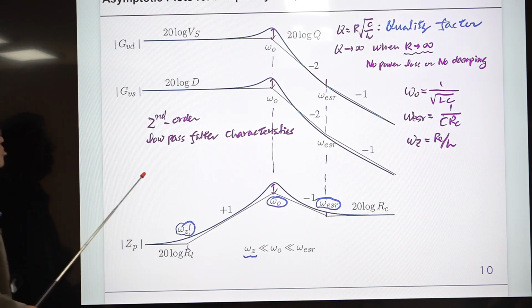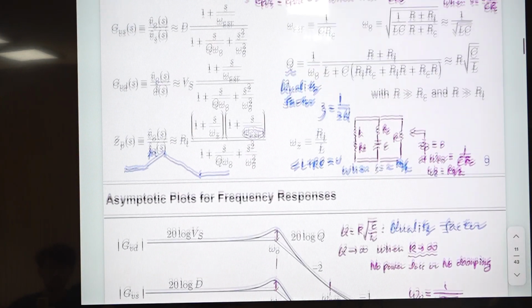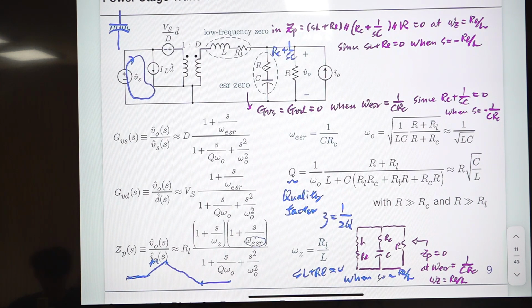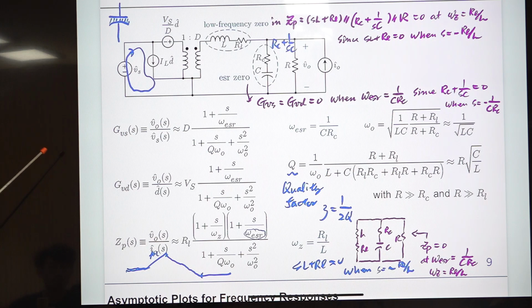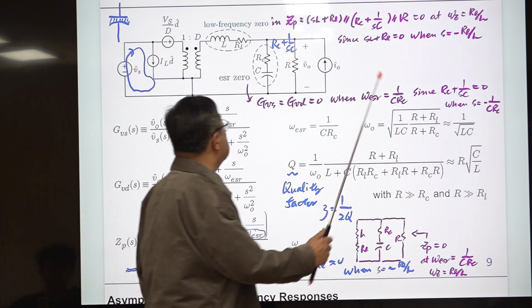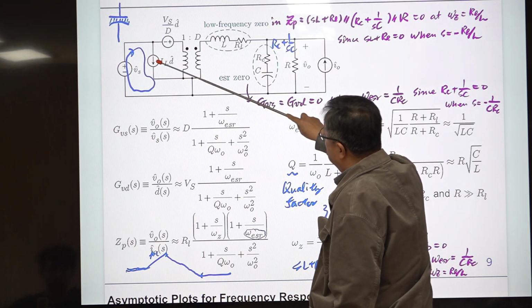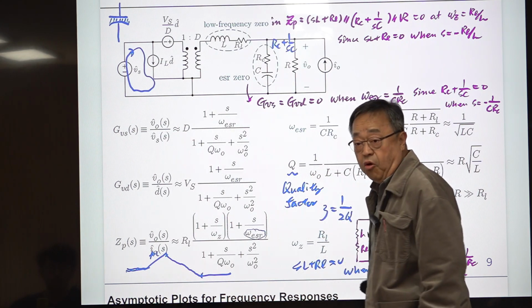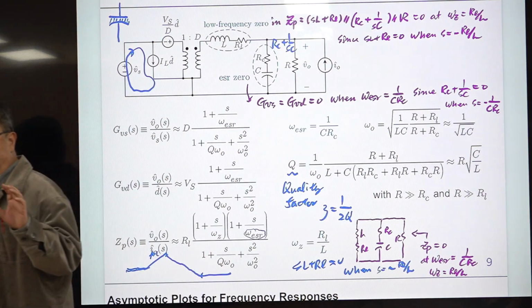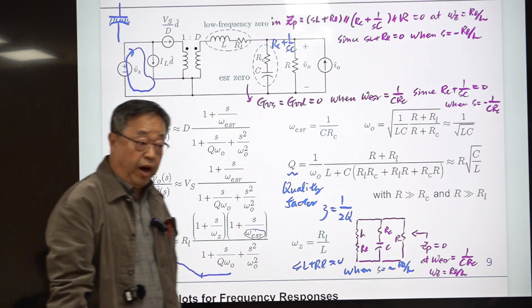This is previous lecture slide, and I think I made one mistake in the last lecture slide. This one is about the transfer functions of a converter. So we went through the GVS derivation, GVD, and we talked about the GPS. When evaluating the GPS, you are looking at this circuit from this point, and this one is 0, this one is 0, everything is 0. That means the primary winding of this ideal transformer is shorted. In an ideal transformer, if one winding is shorted, the remaining windings are shorted too, based on the circuit equation of ideal transformer.